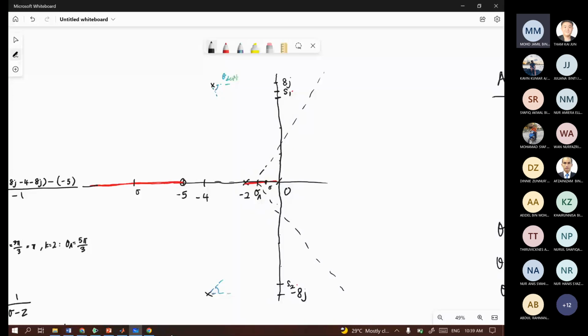If you sketch the root locus from this point here and then cross this j omega axis crossing, you will realize that it will cross the asymptote. So the root locus coming from this breakaway point here is not the one that crosses the j omega axis crossing. The branches that cross it come from somewhere else, not from this breakaway point. So it might come from these two poles here.